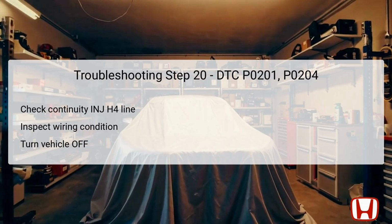If checks fail, repair any open conditions between the PCM and the number 4 injector to restore the circuit. This checking helps maintain the overall efficacy of the injector circuits, which is vital for optimal engine performance. In troubleshooting Step 21, focus on verifying continuity in the INJL4 line.